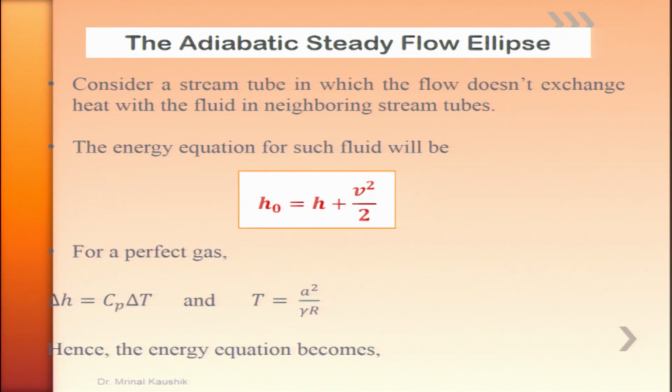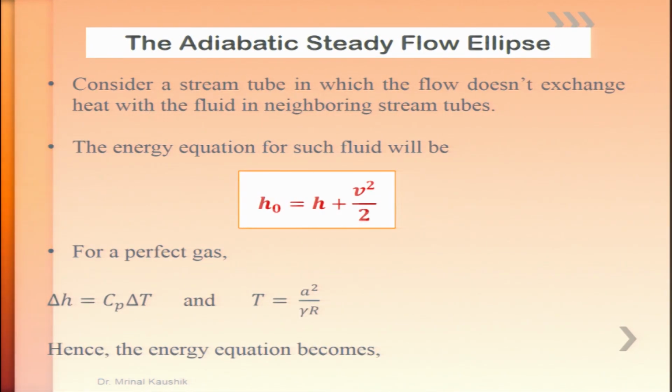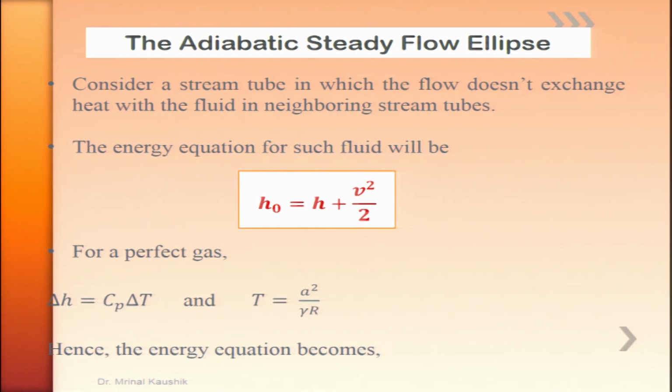Now, we keep talking about various flow regimes, about fluid mechanics, fluid dynamics. In our case, since the fluid is air, aerodynamics, gas dynamics, rarefied gas dynamics. This classification can also be done with the help of a non-dimensional speed, that is nothing but the Mach number.